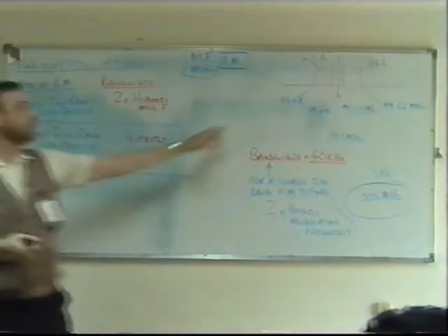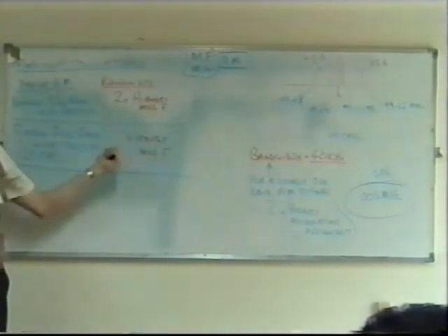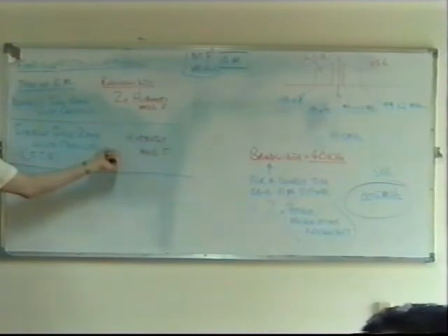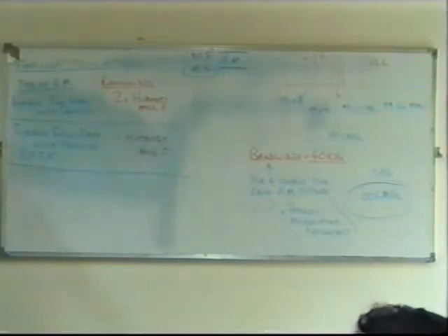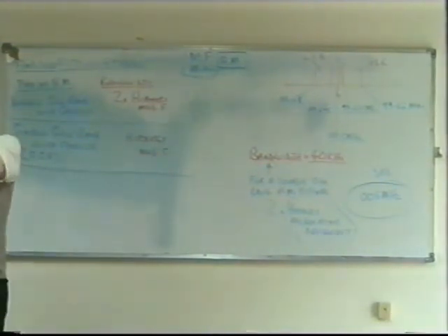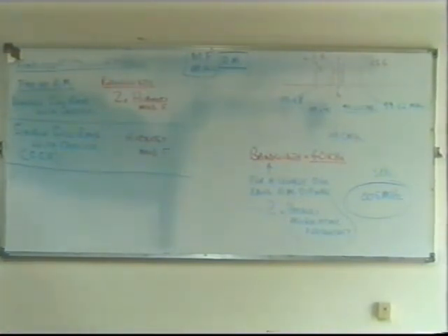I'll tell you where this is mainly used. This is used in HF communications. Basically what happens is this. The operator can choose either his upper sideband or his lower sideband, just by a switch on his control. He listens first. If he gets interference or complaints that there's interference, he'll switch to the other band, and maybe it will cut out the interference. That's all.